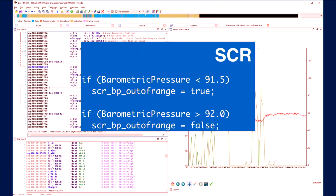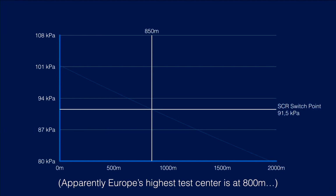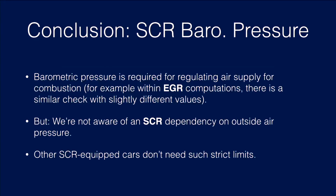Okay, we continue to look. We found something here that looks like this. There's a barometric pressure sensor that senses the pressure of the air and compares it with a value. And if we look at how pressure is related to height, we see that what they check against is 91.5 kilopascal, which corresponds to 850 meters, and apparently Europe's highest test center is at 800 meters, which may be a coincidence or not. But above that point, they reduce the SCR system as well.